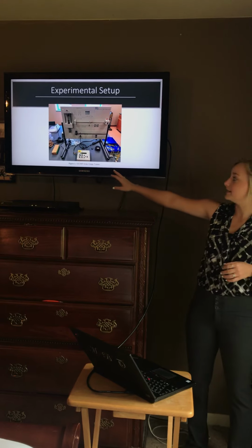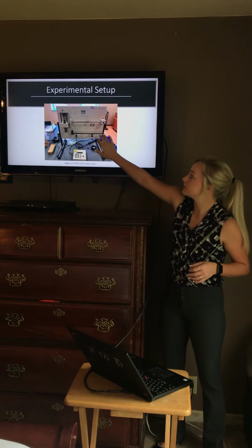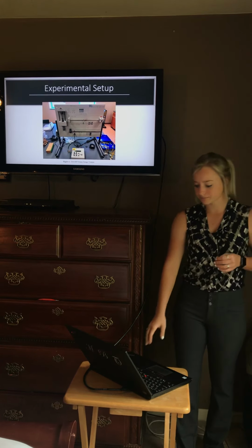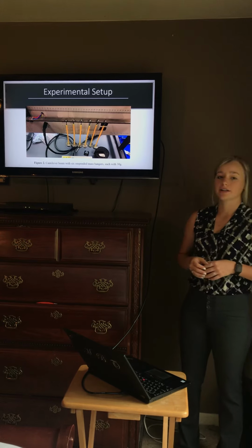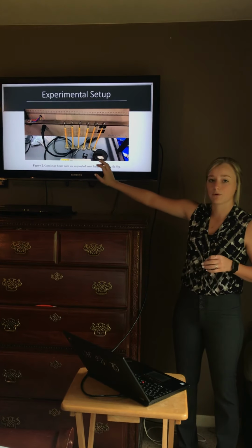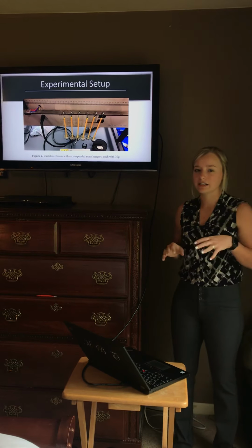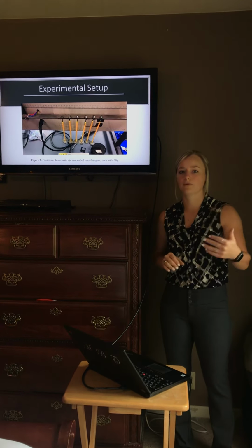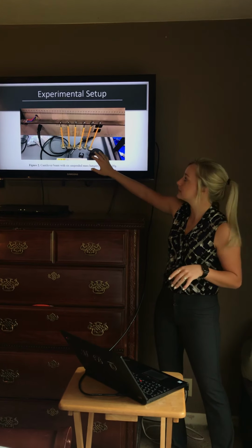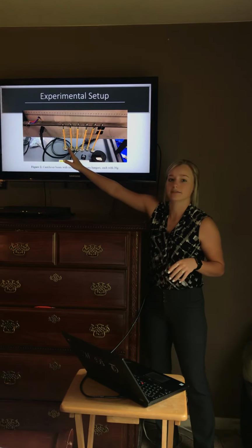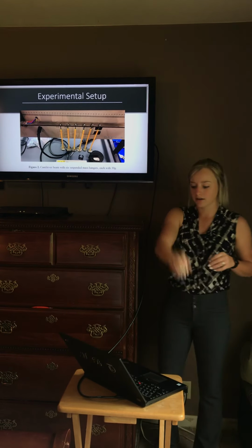So this right here is the SM1000 strain gauge trainer. Along this point right here is our actual cantilever beam. Right here is where we have 6 suspended masses along the cantilever beam, and I will go into detail how exactly this was set up when I move into the procedure, but just note that these are evenly spaced and they do not start right at 0. They are offset from the left-hand side a certain extent.